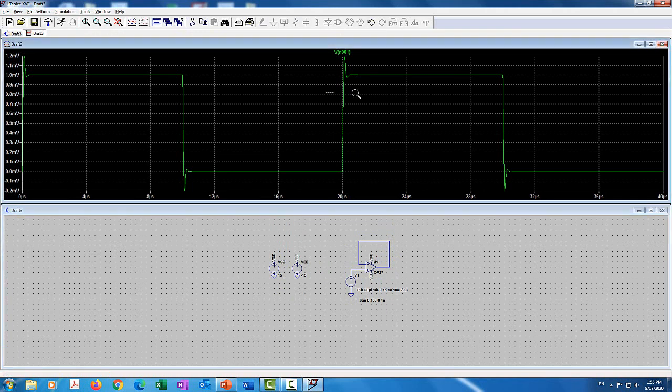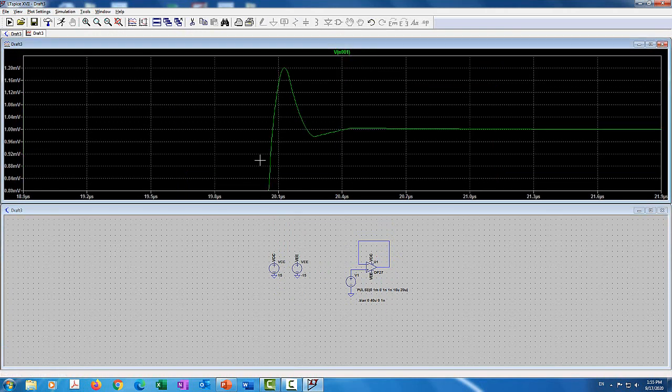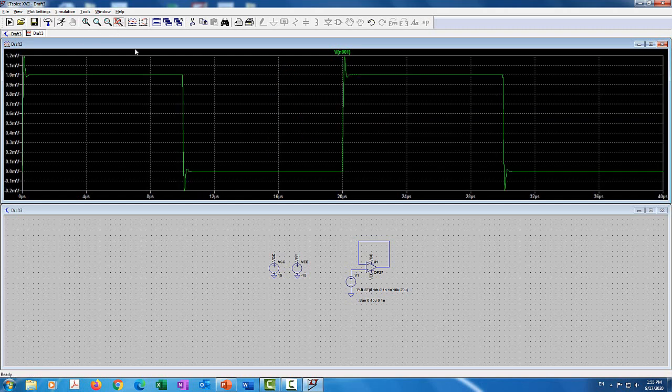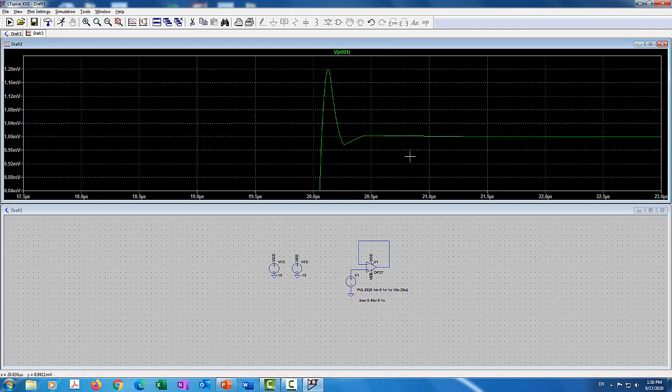And now you can see the sine wave as it goes up and down, right? It's a second order system for sure, and it does have that step response that we expected, because we have peaking in the frequency response. We end up having overshoot. This is called overshoot. It's not bad. 20% overshoot is not a bad metric. If it goes too high, it might have stability issues.